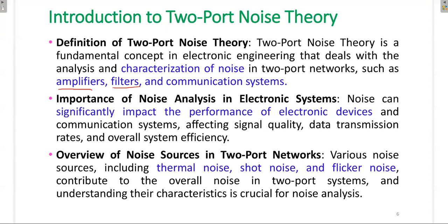Importance of noise analysis in electronic systems. We know that in communication, noise can significantly impact the performance of electronic devices and communication systems, affecting signal quality, data transmission rate, and overall system efficiency. Ultimately, the rate at which we are transmitting depends on the effect of noise, because we always consider the signal to noise ratio. If the signal to noise ratio is better, we can transmit data at a larger rate so that we can increase the overall efficiency of the system.